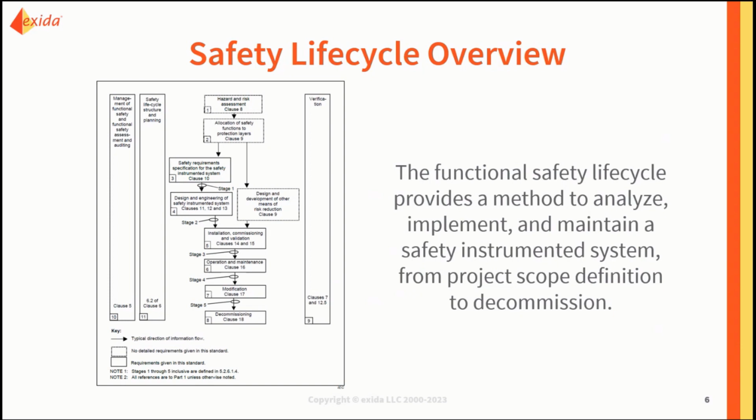After FATs and SATs, you would be able to bring your safety instrumented system online and then document the performance of the safety instrumented system by making sure to collect all data on process demands, on failures, and proof test performance. If your safety instrumented system isn't performing as assumed, you can make modifications to it with an MOC process. And ultimately, at the end of the life of your safety instrumented system, you would do decommissioning.